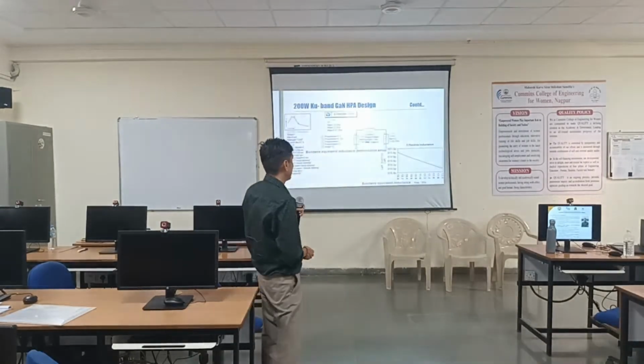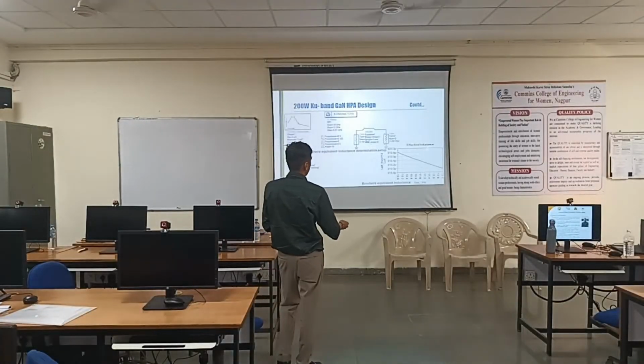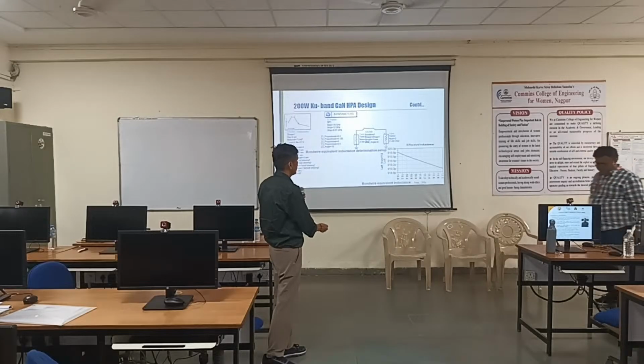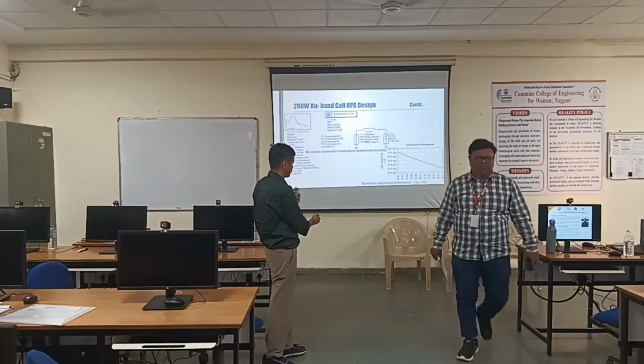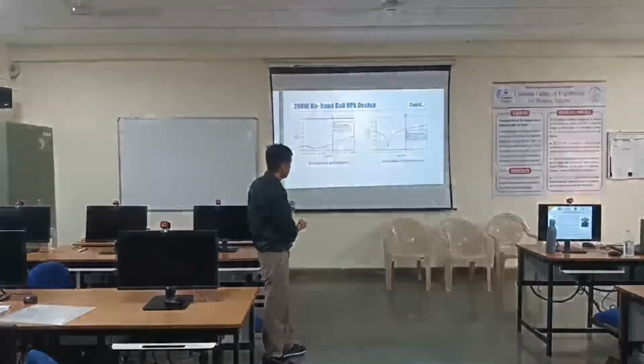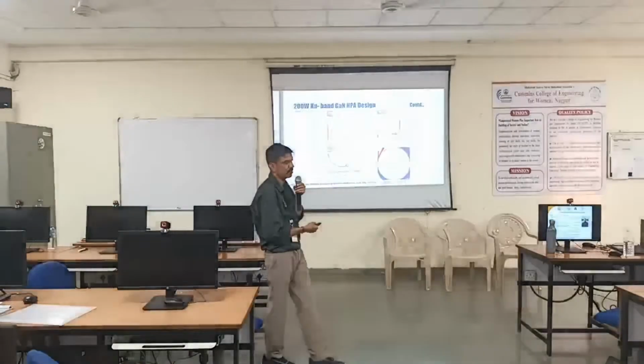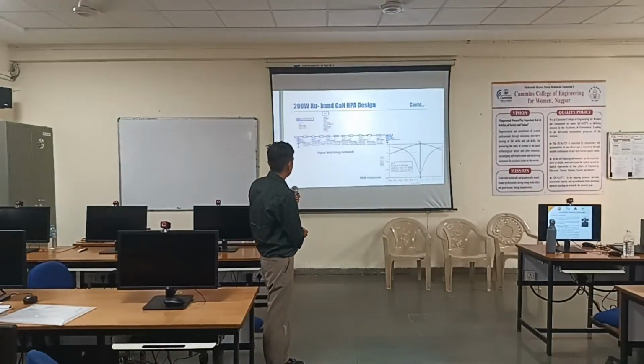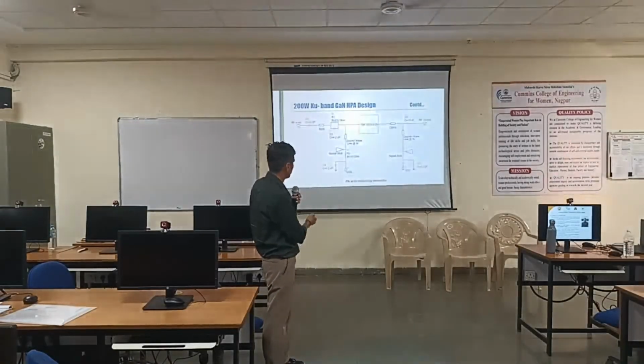So that is the real challenge. So I did the study to calculate the effective inductance offered by the bond wire over the frequency. I calculated this in picohenries. I did a lot of analysis for this because that was the only job I could do. So I proposed this 200 watt PA, something like this.